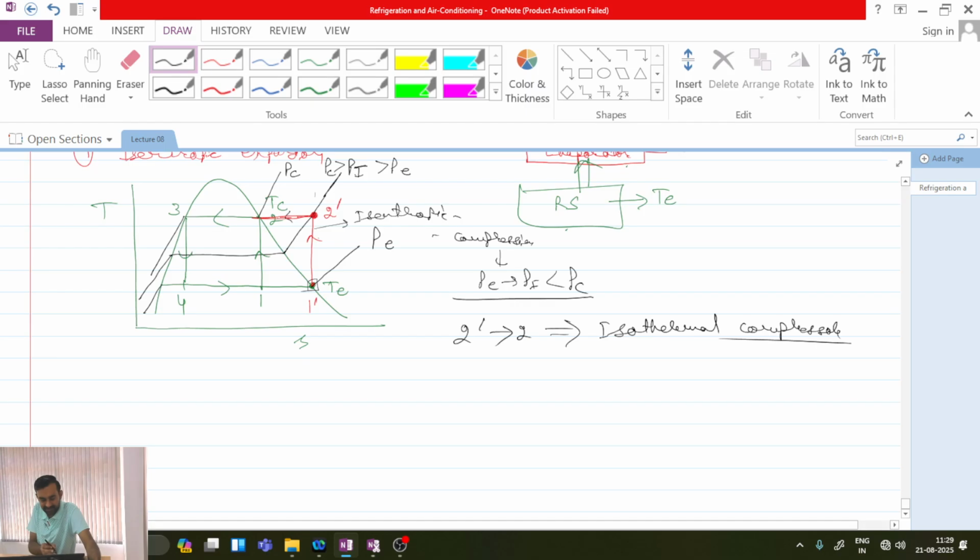So the process inside the isentropic compressor has to be very fast, whereas in an isothermal compressor, if you do compression by a small amount, then you should also reject the equivalent amount of heat so that your temperature does not increase. Because of the compression process, what happens? If you have a piston cylinder system and all of a sudden you press the piston, what happens?